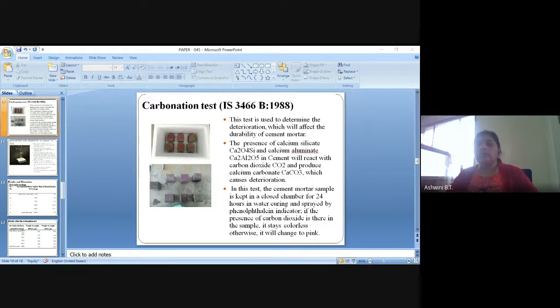In the carbonation test, there is an increase of 2% in weight for the 20 and 30% replacement. So, as the result shows, we can replace only 20%. From this research work, the river sand can be replaced with sea sand up to 20%. Thank you.